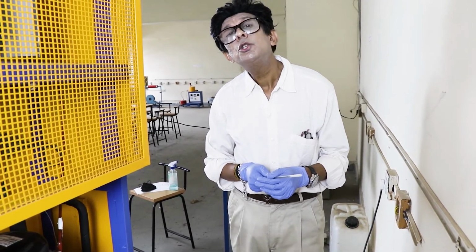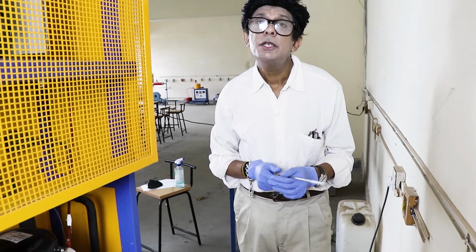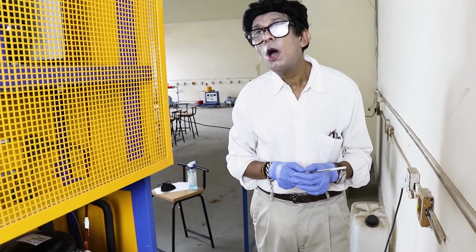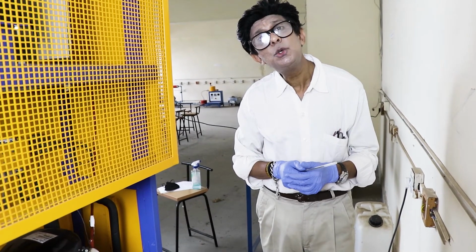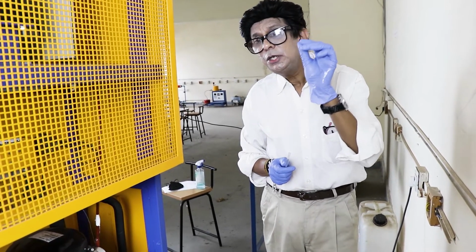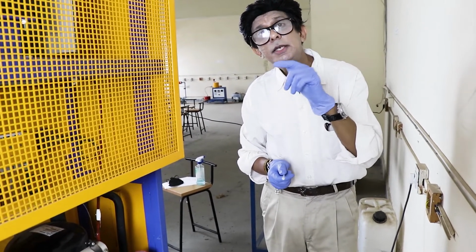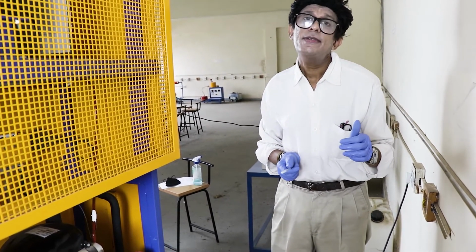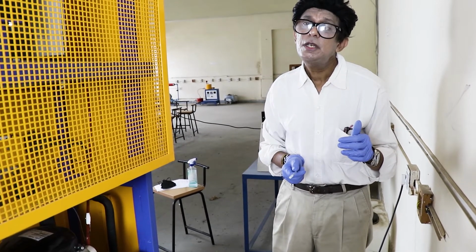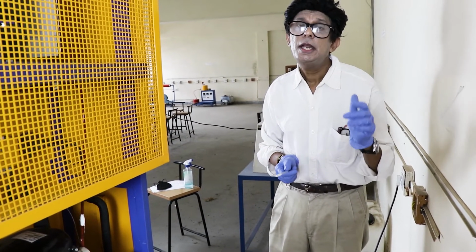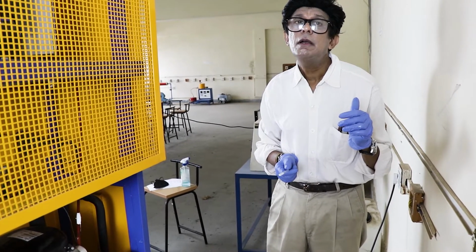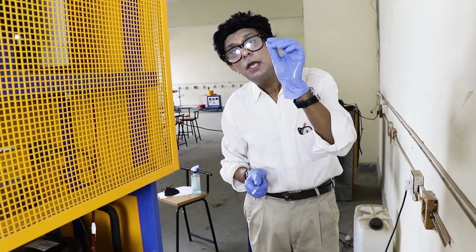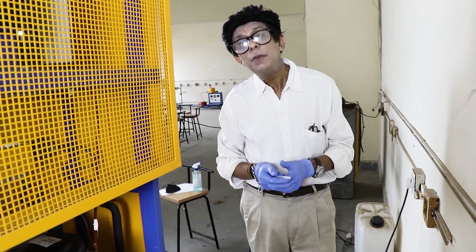the refrigerant through a closed confinement, maybe a small tube of diameter 1 to 2 mm, and the pressure drops when the high pressure refrigerant passes through such a small diameter tube, which you can see over here. When it passes through it, the pressure drops because it has to face the friction. So friction is causing the loss in the pressure head, and we are having the expansion because of the friction encountered by the refrigerant in the small opening of the capillary tubes.